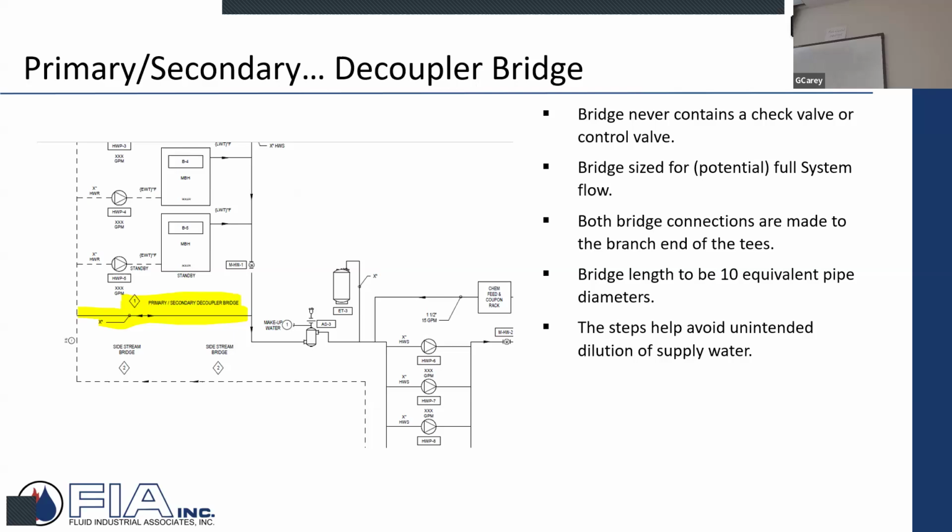Chiller barrel or whatever, they don't want to reduce it too low. Yep, you're not taking that refrigerant, that cooling away, and it'll freeze. So there's minimum flow. So sometimes if you dedicate pumps to the chiller, you take away that concern because you have the adequate, appropriate flow.